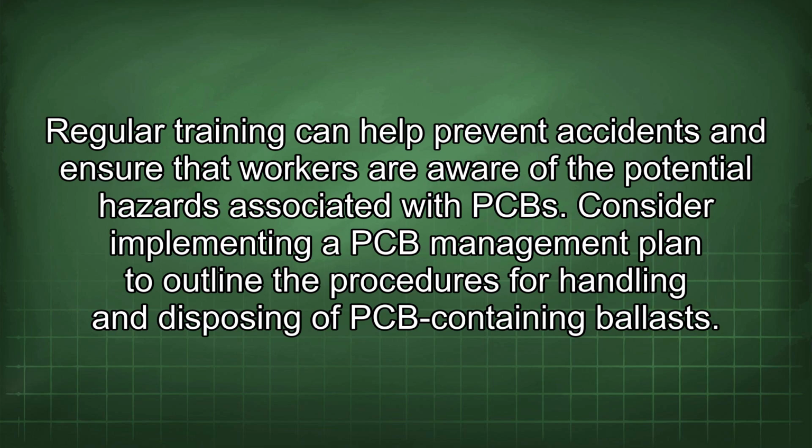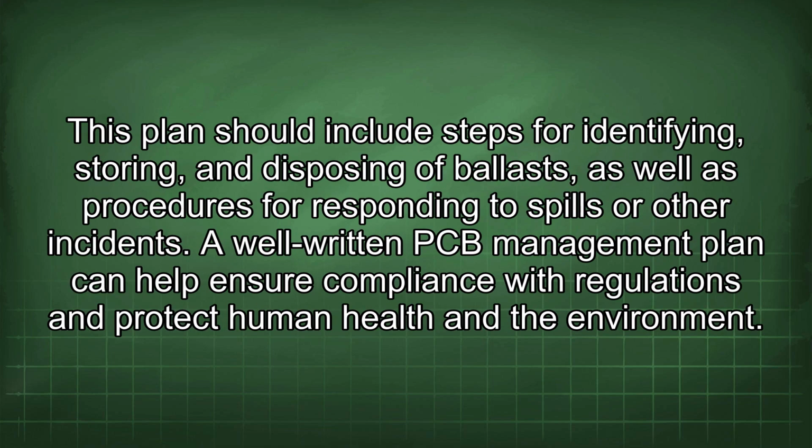Regular training can help prevent accidents and ensure that workers are aware of the potential hazards associated with PCB. Consider implementing a PCB management plan to outline the procedures for handling and disposing of PCB-containing ballasts. This plan should include steps for identifying, storing, and disposing of ballasts, as well as procedures for responding to spills or other incidents. A well-written PCB management plan can help ensure compliance with regulations and protect human health and the environment.